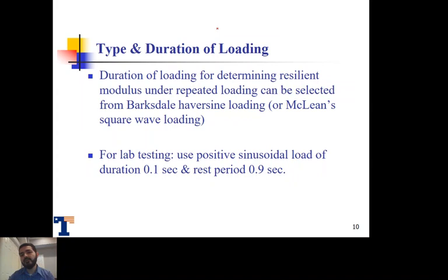The duration of the loading for determining the resilient modulus under repeated loading can again be selected from the graph that I showed you before. Mainly it's from Barksdale's haversine loading or sinusoidal, they're similar. Or there is another one for McLean's square wave loading, but as I told you, the square wave loading is not that frequently used compared to the other one, so that's why I would still recommend you to look into the Barksdale loading mainly.